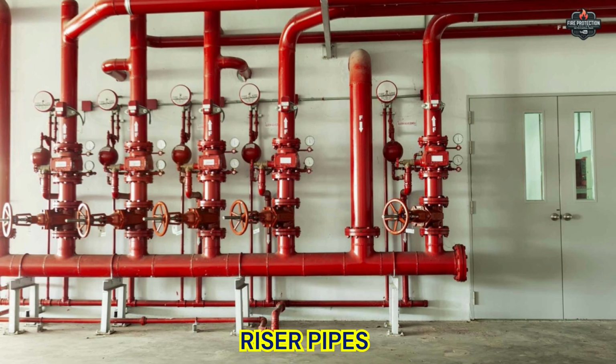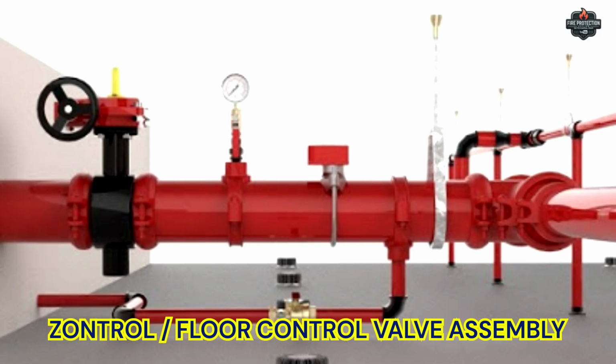This is a typical riser system installation showing gate valve, alarm check valve, flow switch, and the bell. This is a standard zone control valve assembly having butterfly valve, flow switch, and test and drain valve.